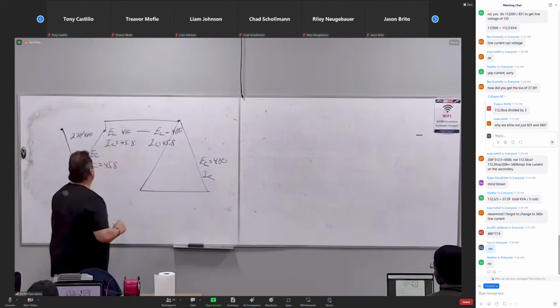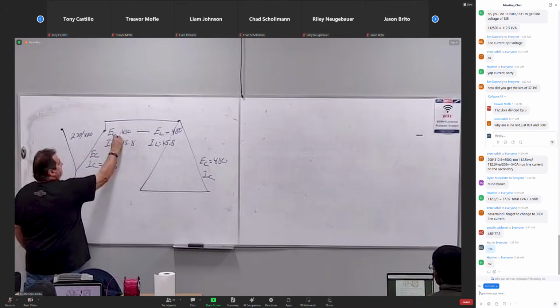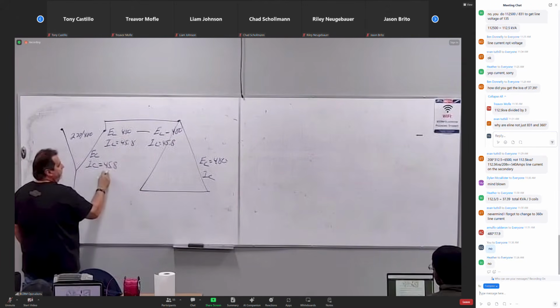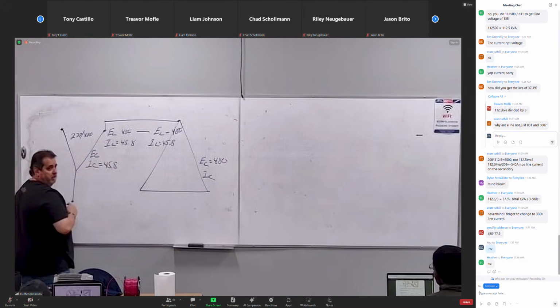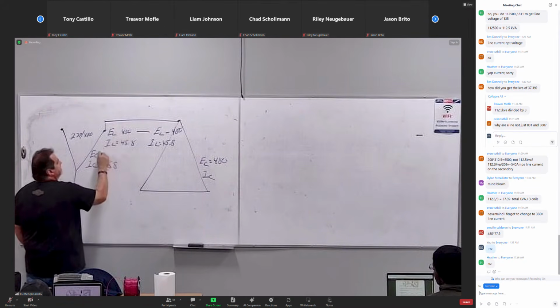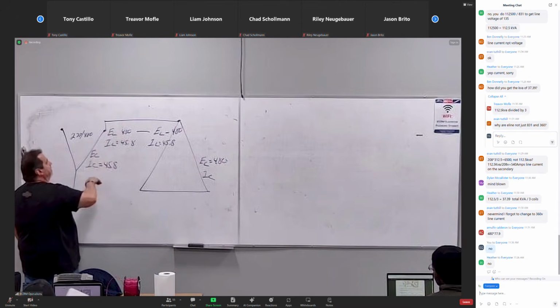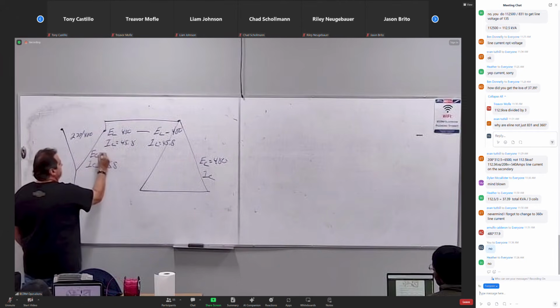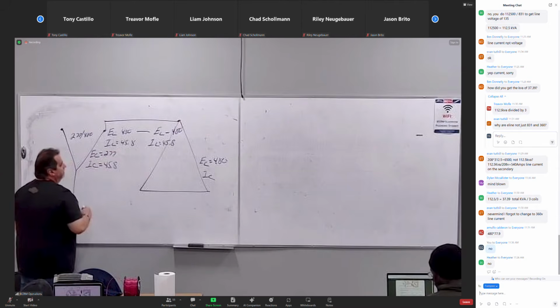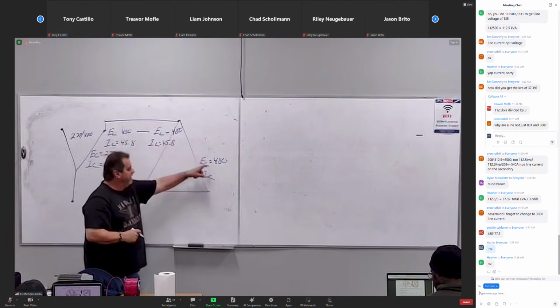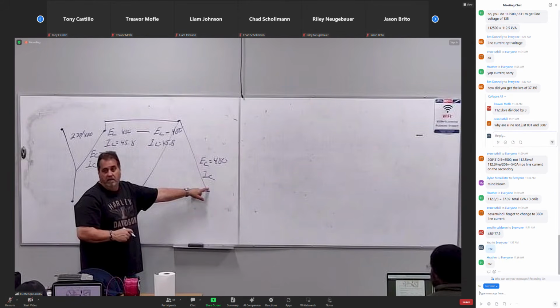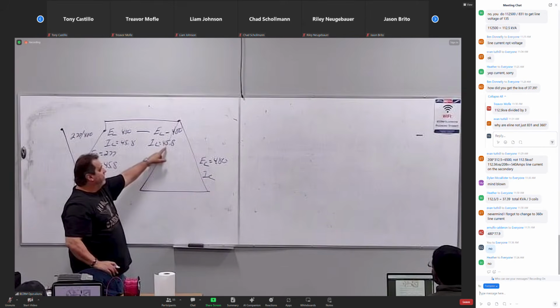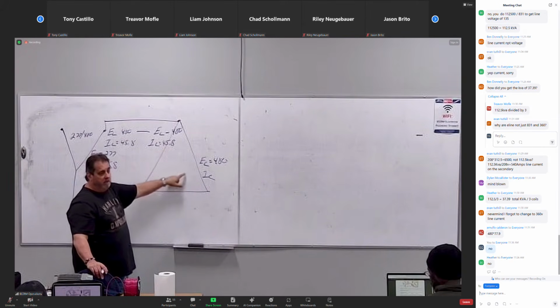If this stays the same, 45.8, what must change? This, agreed? We know this value here is less because line is always greater. Line's greater, I always draw it on top. This equals 277. Over here, this stays the same, this must change. How much does it change by? The square root of 3, right? So I'm just going to take the 45.8 and divide it by 1.732.